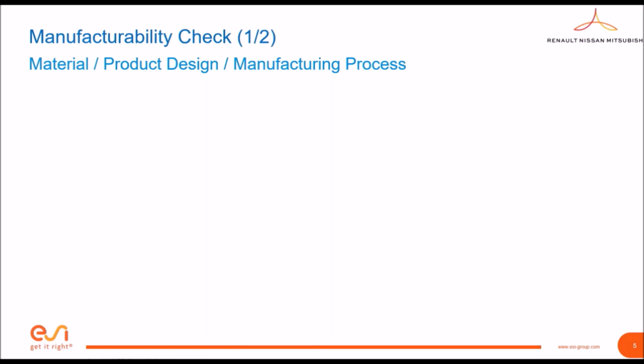Of course, it also depends on what stage of product development we are in, if there is a possibility to make a feedback to the product designers or not. So if it's a part to be produced by the foundry and the part design is owned by someone else, it's probably too late for any modifications. However, this step certainly helps to understand the risks during production and could possibly also help to factor in these costs during the quoting process.